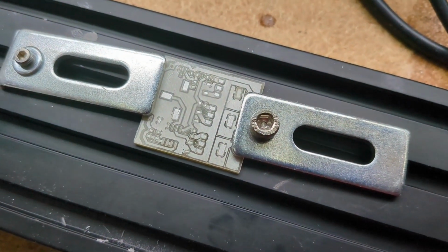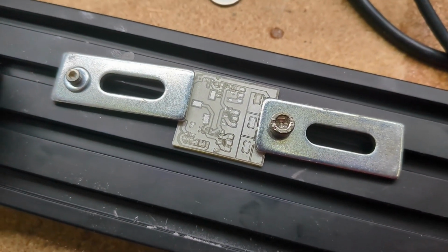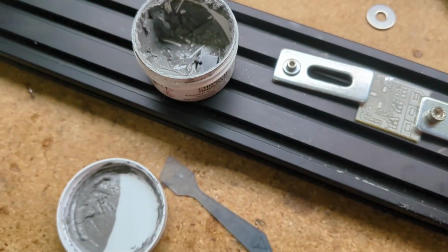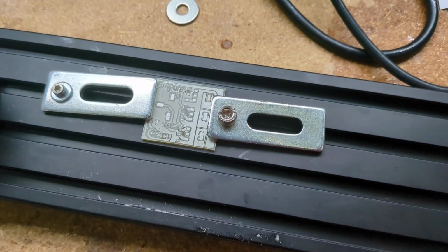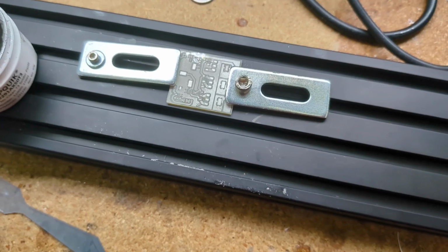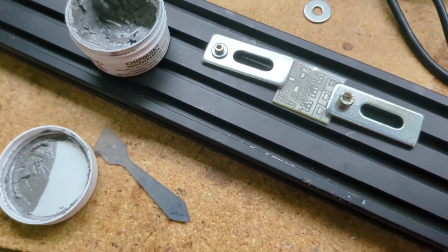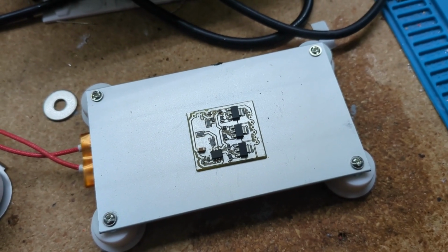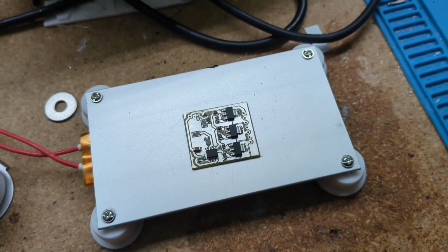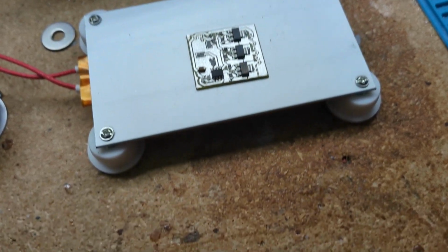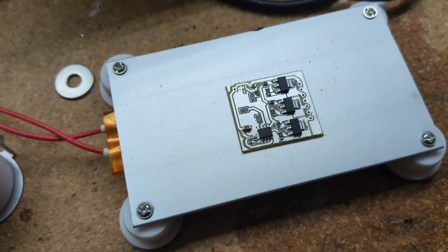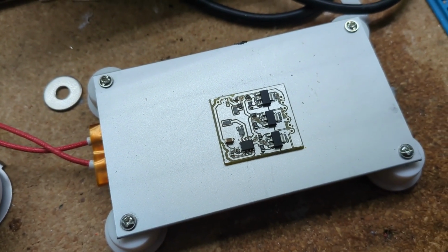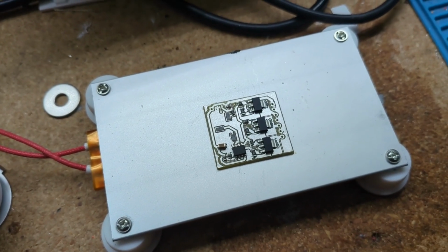Okay, I got the solder mask cleaned up and clamped down, and I got some solder paste. So you just put the solder paste on, and then I'll put it on a hot plate. Okay, I put on what I think I could put on, and I'll just hand solder the rest. So this hot plate is just heating up the solder and setting things, so it'll do a lot of the work for me. And then I just got to finish up with a soldering iron.